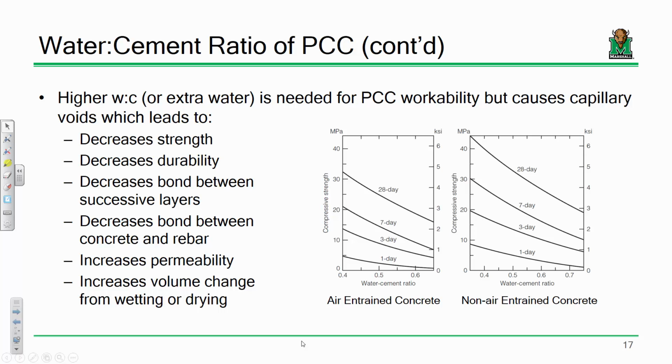Now, the long and short of it is a slump test gives you at least some numerical measure of workability. The larger your slump, the higher the perceived workability of your mix is. And throwing more water into the mix will increase workability. But the problem is that if you start throwing more water into the mix, you will decrease your strength. So there is a trade-off, okay? And that's going to be one of the very first values that we select when we start getting into design: what's our water-cement ratio.